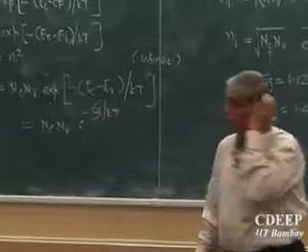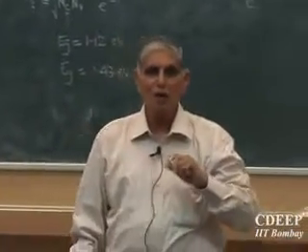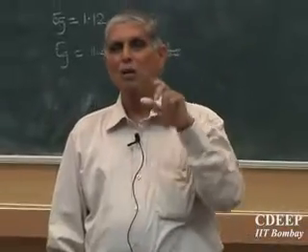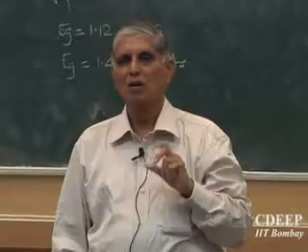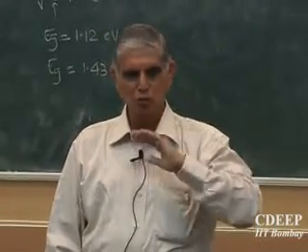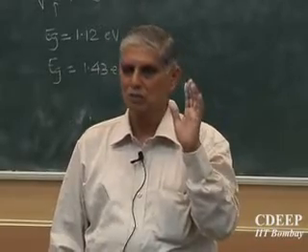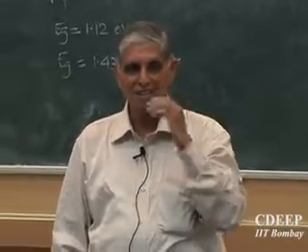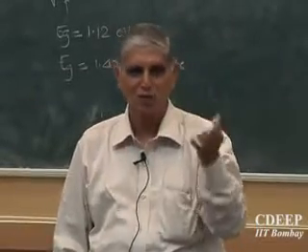I want to correlate how far I am away from Ei. But I don't want to really worry about values of Ec and Ev, so I start measuring my energies with reference to Ei. What is the Ei value typically? Eg by 2, but not exactly, because the effective masses of electrons and holes are not the same.